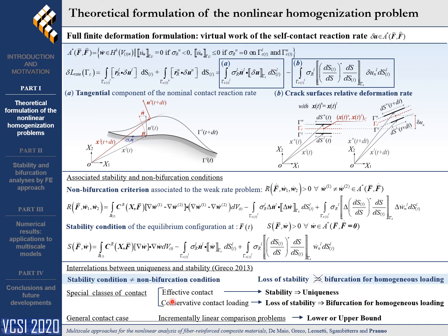In the more general case, upper and lower bounds of the critical loads can be obtained by means of an incremental linear comparison problem.